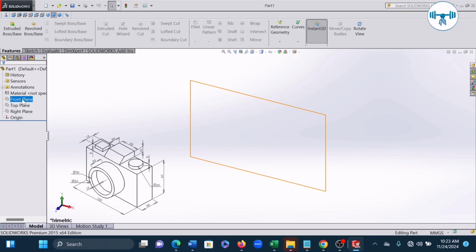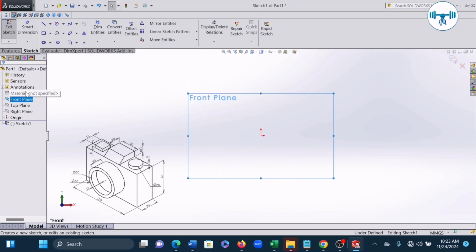So I'm going to open this front plane. You see, I'm going to click on it and I say sketch. Can you see? If I click on it, a small menu pops up, and then I'm going to click sketch. So you should be rest assured every sketch I am doing now is on this front plane. Okay, and of course there is an indication of my origin. Remember what I said in the first lesson, that every drawing must start from the origin. So I'll come to my sketch and I'll pick line.